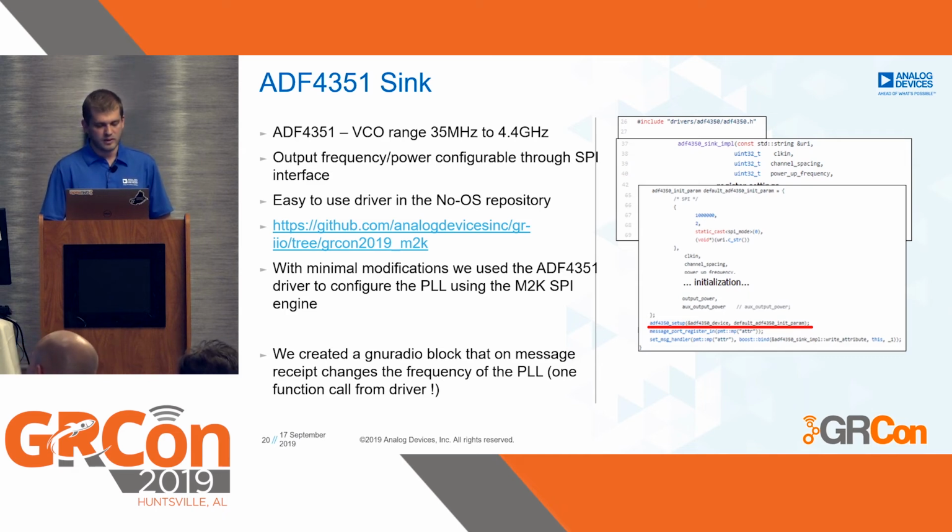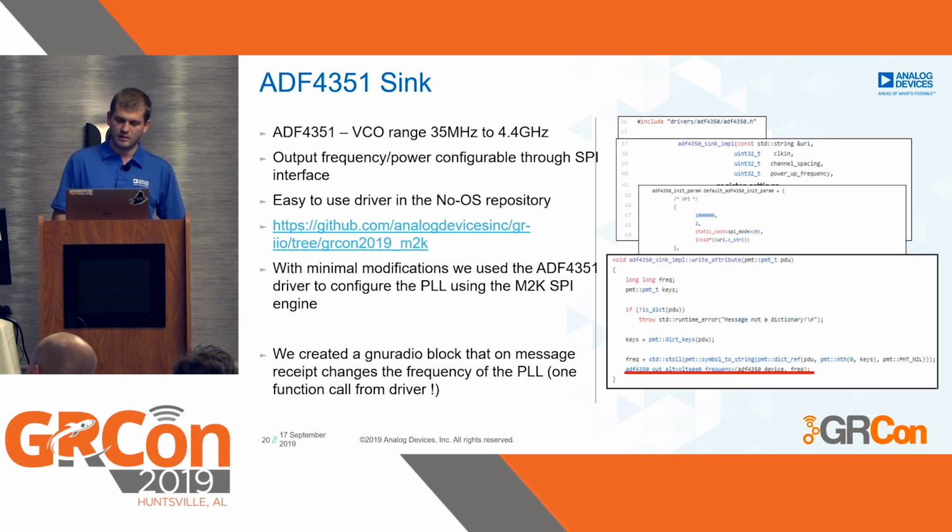The second part of interest is the one that is underlined here, the ADF4350 setup. This function comes straight from the driver. You just call this function, and the driver handles all of the initialization for you. Then we map whenever you receive a message using the set message handler, we map that to a function, and then we write the actual function to change the frequency whenever we receive the message.